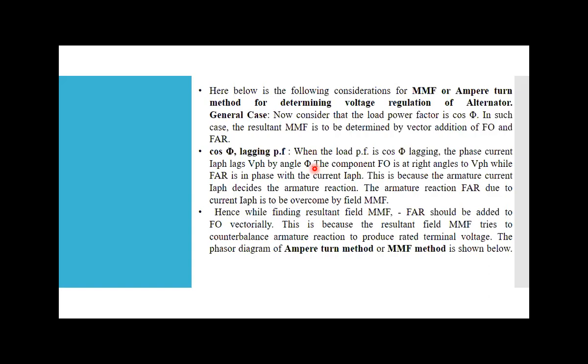Inductive. For an inductive load, my power factor is lagging. And when I have an inductive load, you are aware that my current is always lagging the voltage by some angle. Suppose my load is purely inductive, then my current is always 90 degrees behind my voltage.